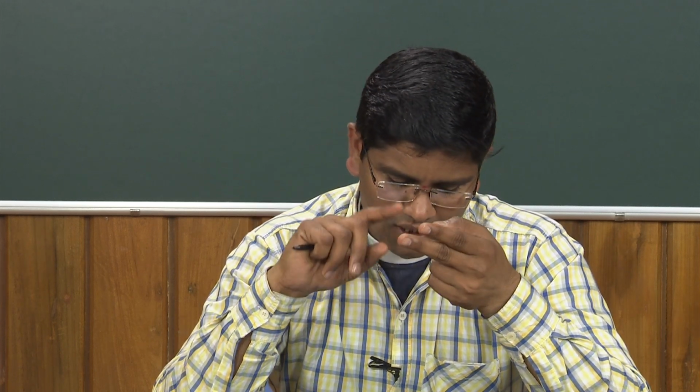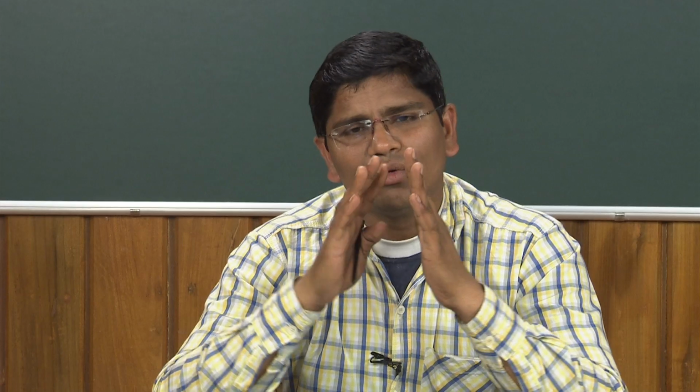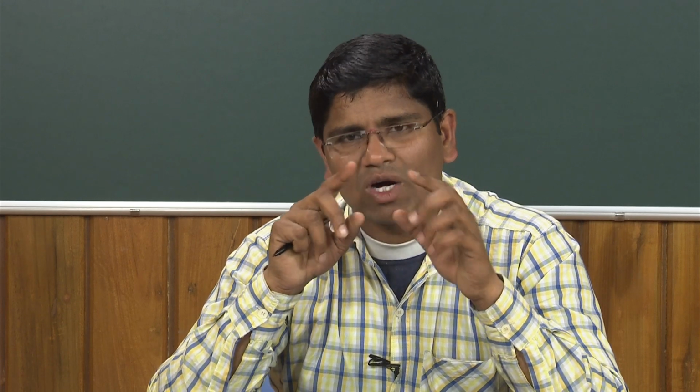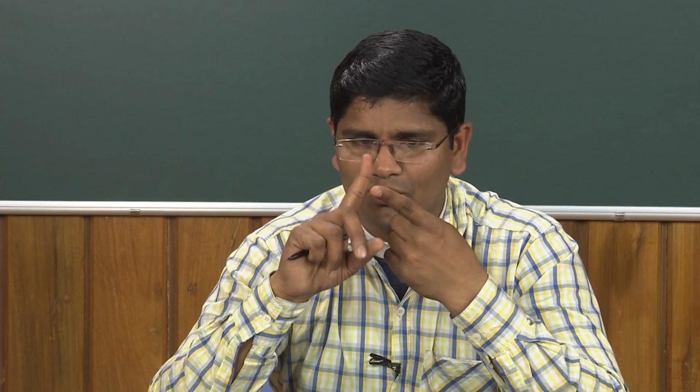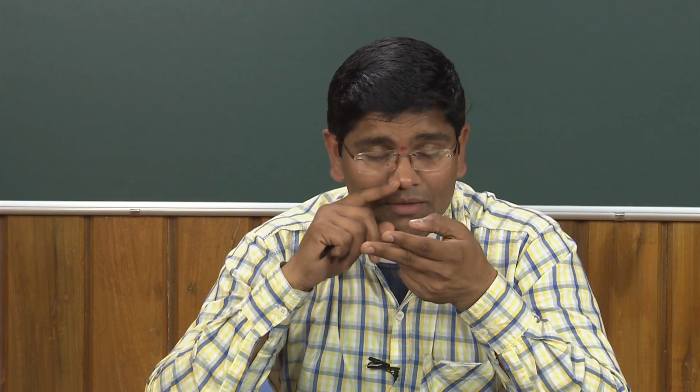A 30 mm nozzle stand-off distance is optimum, because you have to generate as much force as possible to separate the chip and the tool. At the same time, you have to cover the minor axis. From both points of view, a 30 mm nozzle stand-off distance is better.